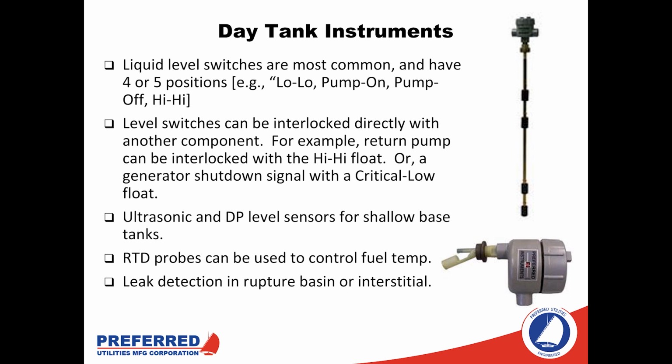So as you can see off to the right, we have a picture of a multi-point level sensor. Now we're not using an analog. An analog is great for determining the exact number of gallons in the tank, but as far as reliability, an analog sensor could possibly malfunction. And typically it's not going to be designed for the total range of the tank. If we have a 3-foot tall day tank, we're going to be using a standardized analog level sensor that could be calibrated for 10 feet originally from the factory. If it was to lose its calibration, now the pump off location or the high level location is going to be feet above the day tank.